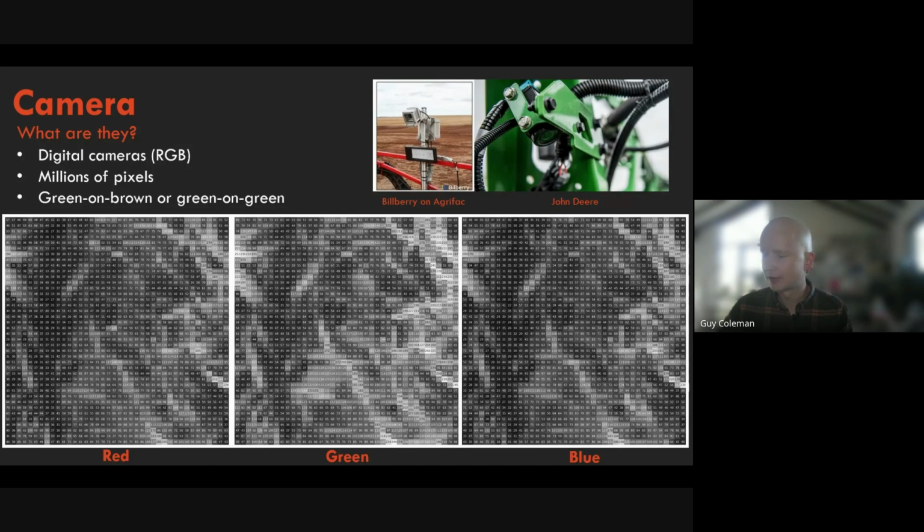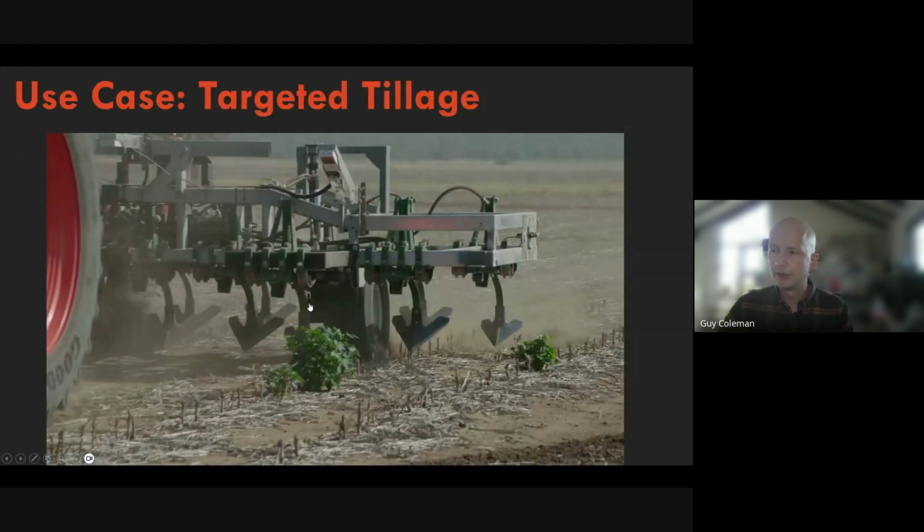And so when you give it enough training data for these more advanced algorithms, where rather than just detecting green, you have an algorithm you train and give a lot of samples, it's just trying to pattern match across all these vast arrays of numbers on many millions of pixels. It always blows me away that this can be done in real time, and you can teach algorithms to detect what is a wild radish in this blur of numbers. It's quite impressive. So that's the camera. And of course, that was the sensor part, and the processor part is embedded in there somewhere.